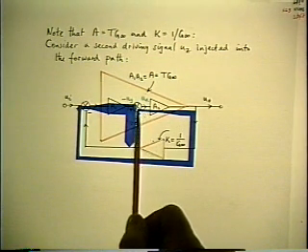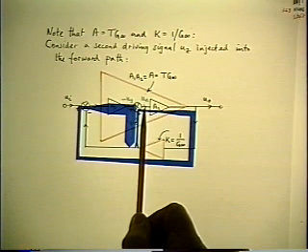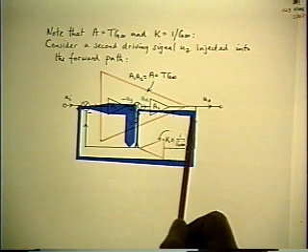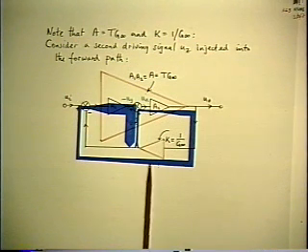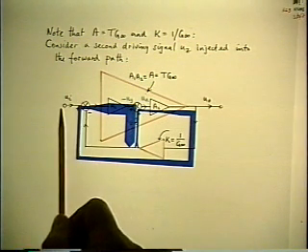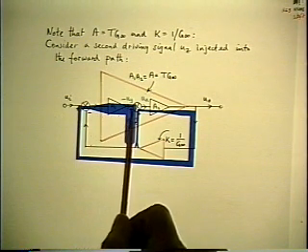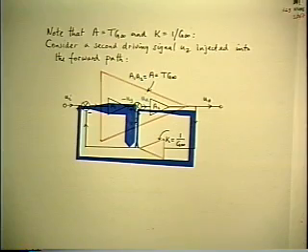The UZ splits into two. The small part of it is UX if the loop gain is large. UX is multiplied by A2, gets attenuated in the K box, subtracted from 0 because the input is 0. Gets amplified again in A1 and shows up as UY.